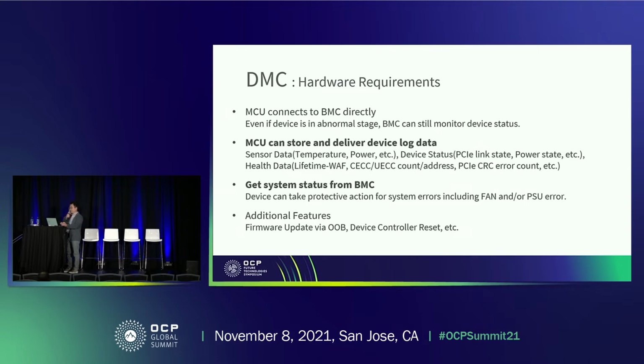The third thing is a different point from a general PCI device. You know, an SSD has more than 100 telemetry data sets. With this data, we can predict the device failure or predict device lifetime and debug failures. For example, WAF, NAND read-write ratio and history, and uncorrectable error counts or correctable error counts for internal memory, like SRAM, DRAM, NAND.